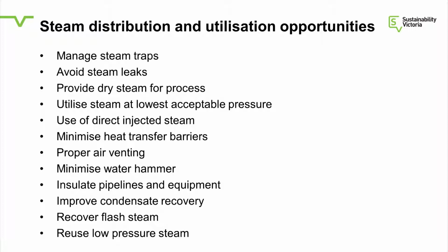So we're only chasing 20% in all the things I've talked about. Put an economiser on, I said 4%, oxygen trim 1%, 1.5%. So all those little things, you might save an extra 5% or 6% by doing all the things that we've discussed so far. However, once it leaves the boiler house, that's when the fun begins.